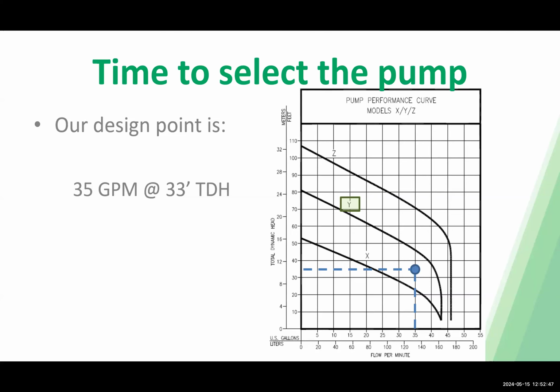The main thing to worry about is how much flow that larger pump may be putting out. That is where you may want to go back and check the velocities that are going through your pipe, as we're going to see in the system head curve section.